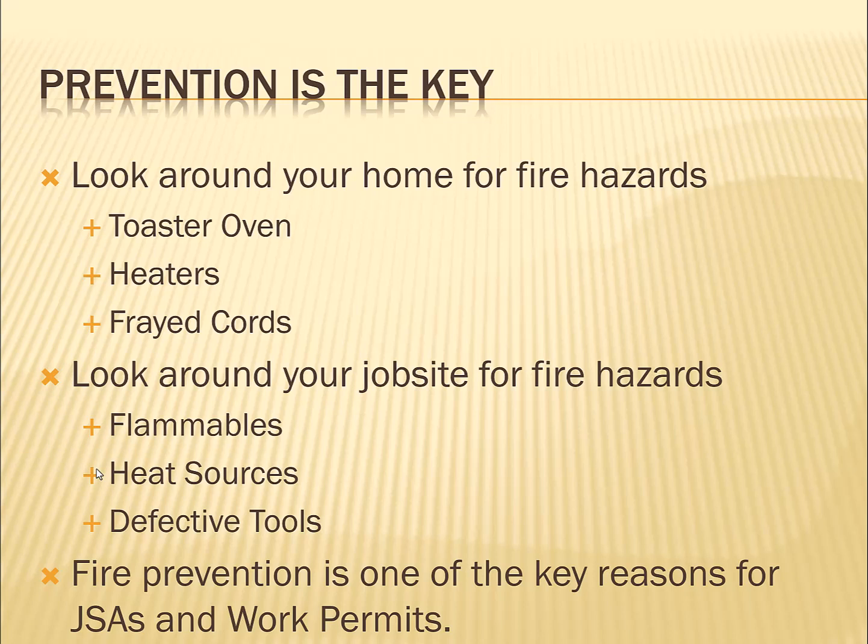And there are different kinds of work permits, and one of them is called a hot work permit, and that's for things that can start fires. It can be just welding or grinding. You create sparks, and therefore that's a fire hazard, because of anything the sparks could catch onto or ignite, particularly in the plants where they've got gases that can leak at any time. And when those flammable gases meet up in the right concentration with sparks, or a spark, that's all it takes.